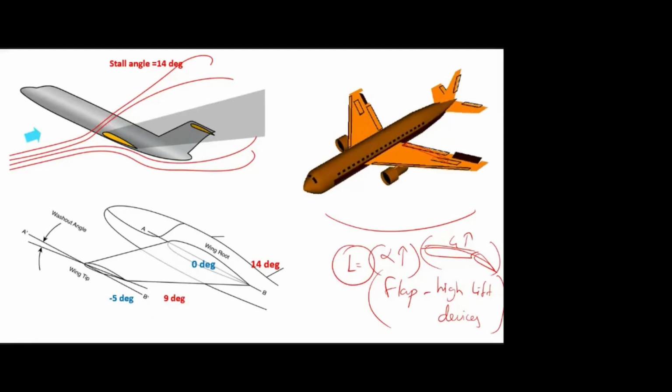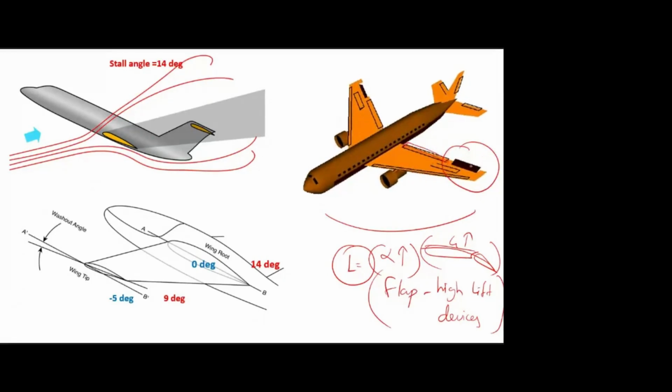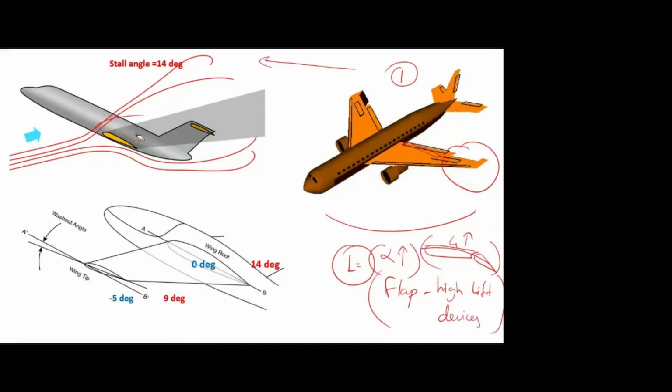The flap will be attached in the inward side of the wing, and in the outward side you see this is called the control surface, the aileron. Using this only we can do all the maneuvers. And assume this aircraft is at the stalling angle. Stalling, as I told, means the flow is completely separated from the leading edge. There is no flow over the wing, right? Complete loss of lift. Assume the pilot mistakenly went to the stalling angle. So now what happens? Flow separates completely from the wing leading edge.